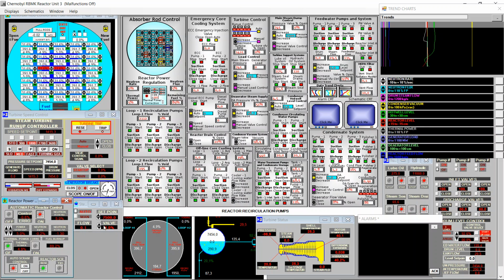The relief valve is close to zero now, so now we will start decrease of the drum pressure because of reactor power decrease. Very good, the turbine is spinning down by itself. I think we don't need the reactor anymore, so I will reduce the power to 2%.